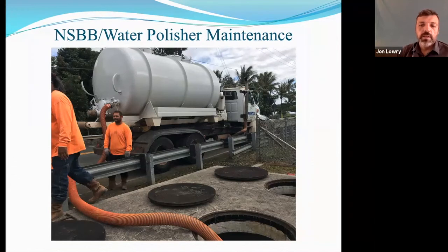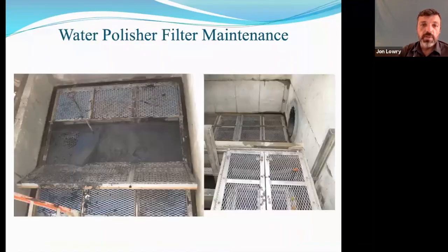So here's a vac truck being used to clean this water polisher baffle box combo. And if you look down in there, you can see this is one of those upflow media filters. The other key is that you have all your filters available and on site during the cleaning. These filters need to be cleaned once the water is actually drained out of the baffle box.